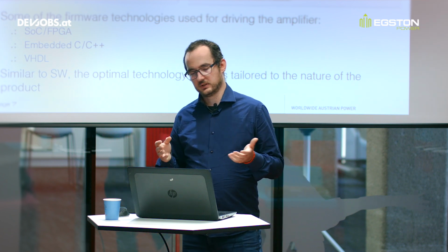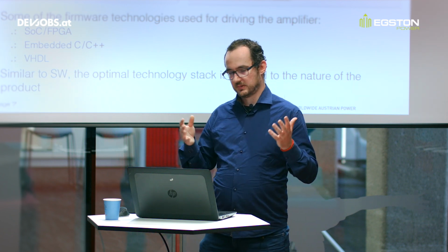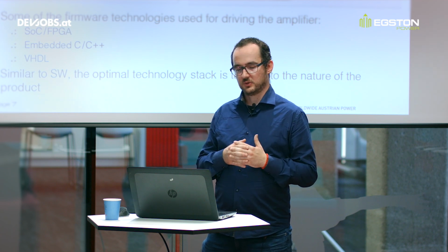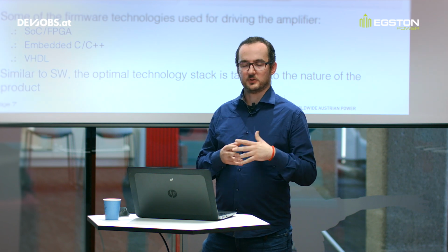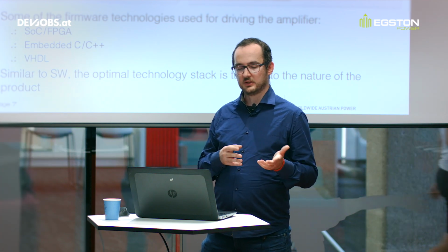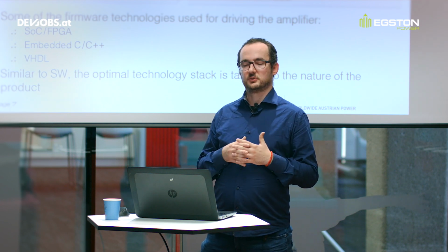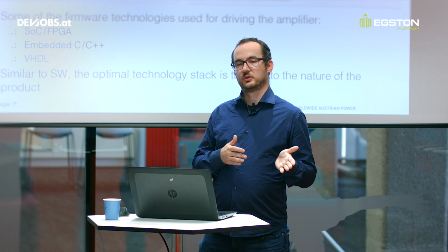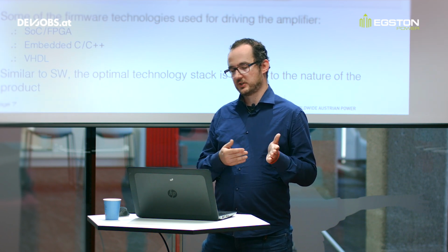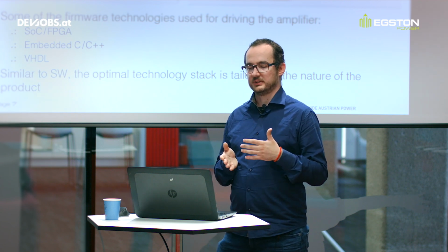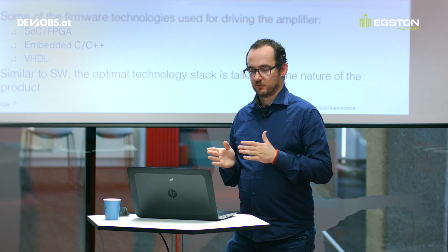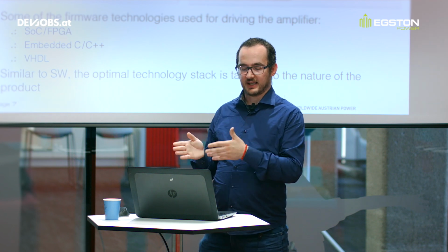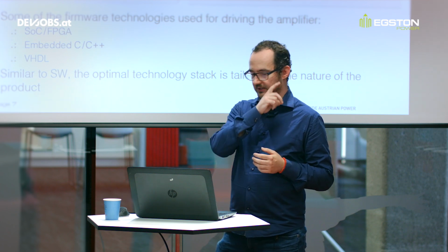In terms of embedded programming, as we already know, on system on chips there are embedded microcontrollers for which we can use either a bare metal approach or embedded Linux, using C or C++ in order to optimize it with some real-time flavors, but also non-real-time flavors where we need to establish a TCP/IP communication in order for the graphical user interface to interact with it properly, to communicate the status of the system back to the graphical user interface, and so on.